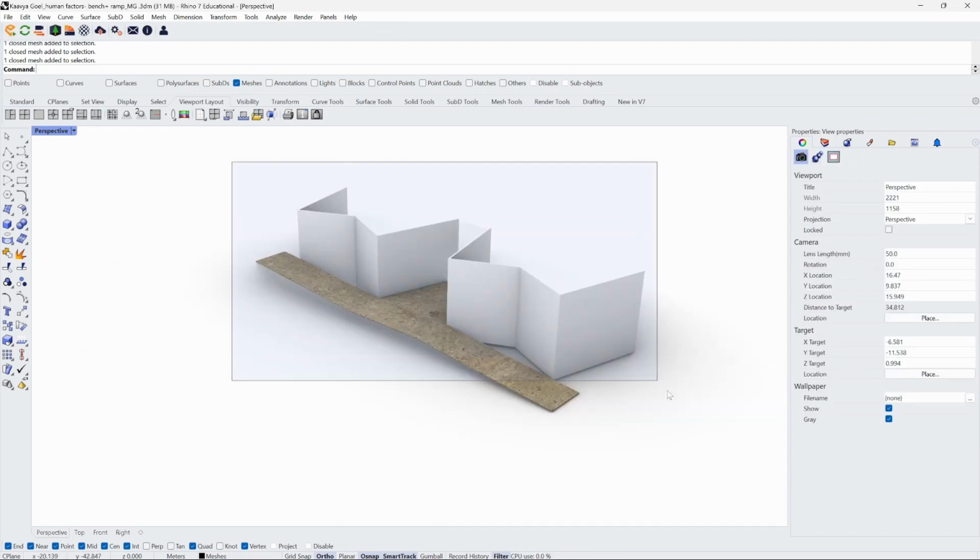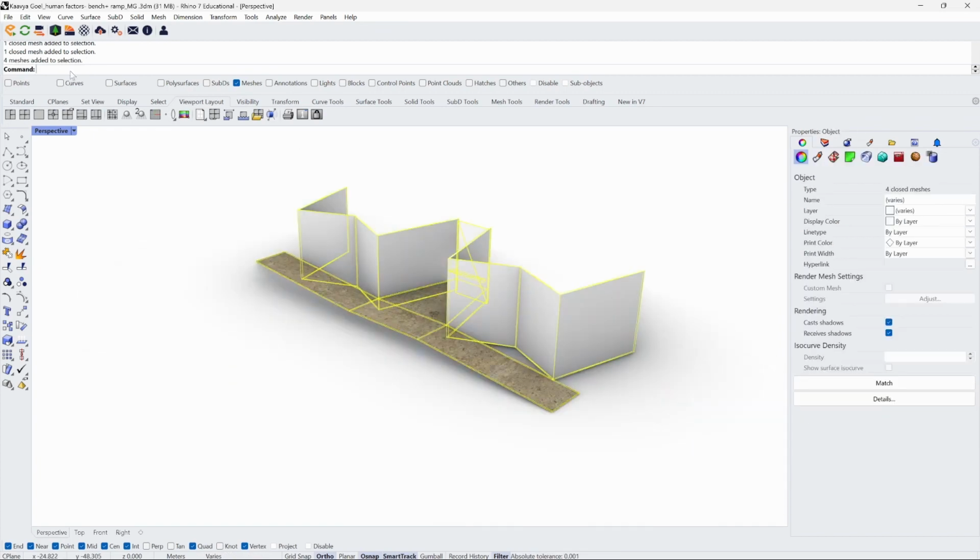Okay, so now just meshes. We can select all of them, perform the command polygon count, and here we have only 136 total polygons, so the meshing operation was quite effective. All the meshes combined in the geometries you use then in Unity, you should not surpass 200,000, otherwise the performance will be suffering in VR.